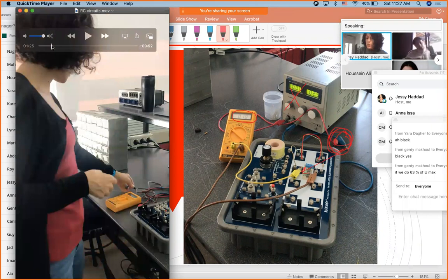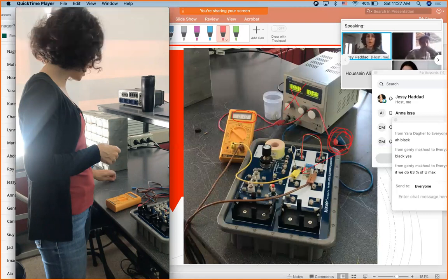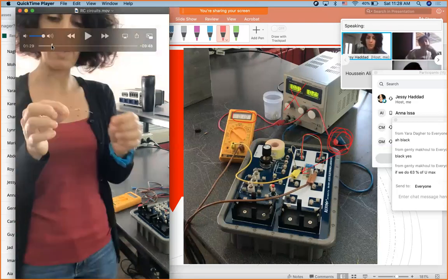You can see it's written on it 330 microfarad and 100 microfarad. This is a nominal value, and I don't know how much you can trust a nominal value. A lot of students in the lab would ask for an LCR meter to measure the actual capacitance of the capacitor, and they would discover that the capacitance is a bit far from what's written on it.